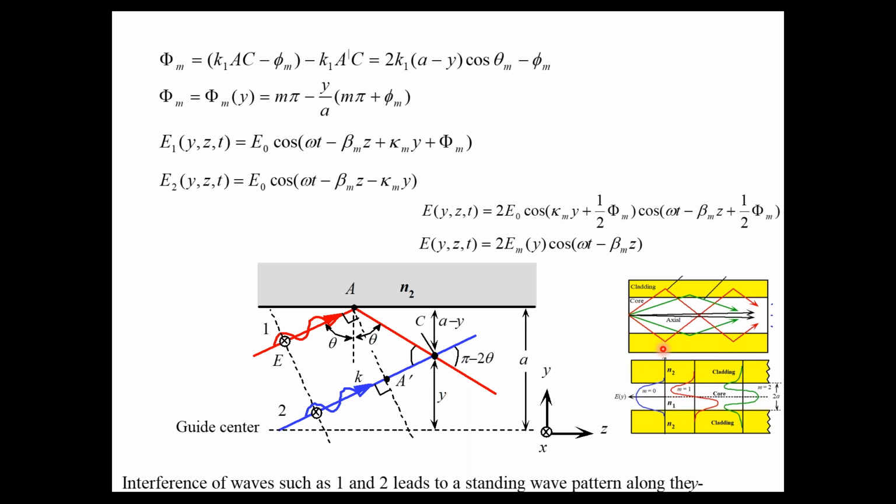And one thing to be noticed here is the penetration into the cladding, as we mentioned earlier, there can be a tunneling. This is a kind of optical tunneling. In fact, this is a forbidden region for the photons concerned because of the lower refractive index, but they tunnel into the cladding. So the tunneling is more for the higher order modes. So this is a higher order mode. Obviously its mode, that is the electric field pattern, is leaking more into the cladding. For a lower order mode, it is leaking a much shorter distance into the cladding.